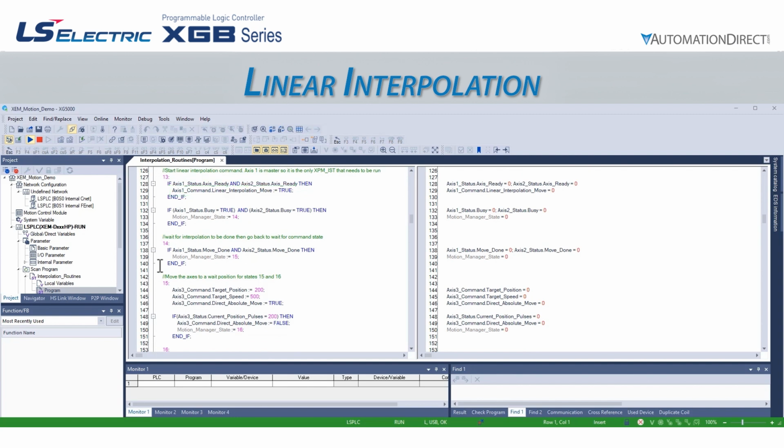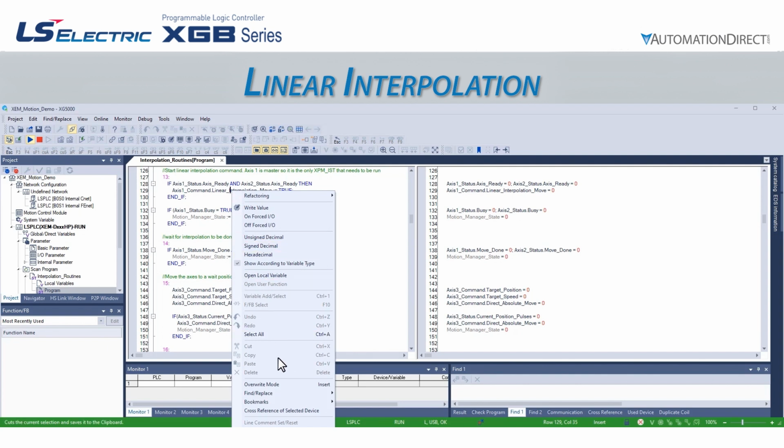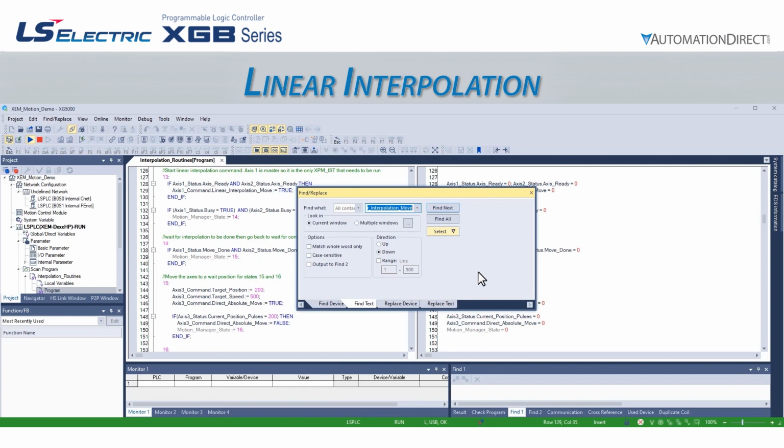Let's run a search to find this bit elsewhere in the logic. We can right-click on the bit and go to Find Replace, Find Text. This opens the Find Replace pop-up window. Let's set the Look-In box to multiple windows, and then select Select All from the Find What drop-down window. It already put the variable name into the search box, and we can now click Find All.